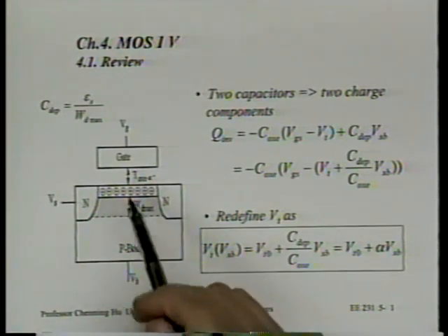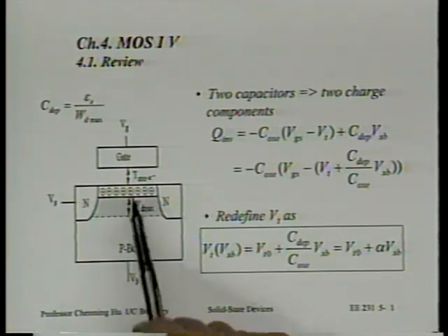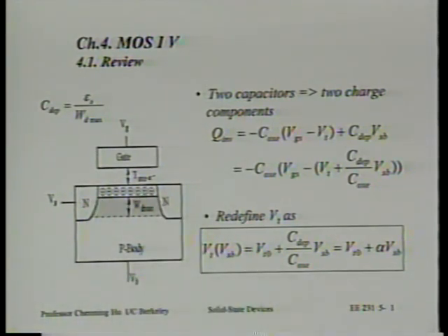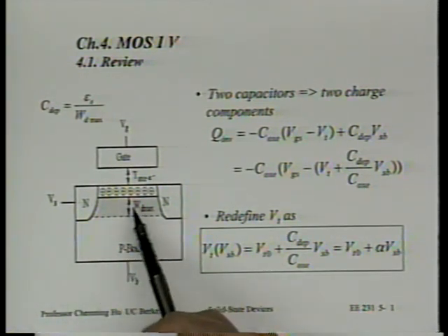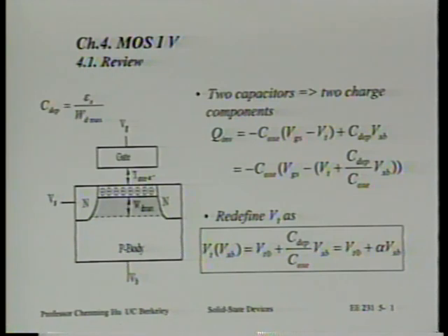And what's the other thing that might have been included in this T ox effective? Polydepletion, right? So, all right. It's okay. So we're not going to carry those explicitly, but we have to think that this oxide thickness perhaps is more than the physical oxide thickness. So once we have done that, we can visualize this inversion layer just as truly a thin sheet of electrons. Is that okay? But I do want you to remember right from the beginning that we do have a depletion layer under that inversion layer. And the thickness of that depletion region is called WD max, right?